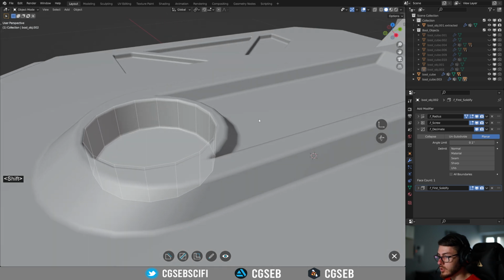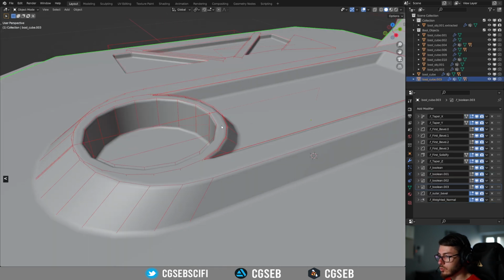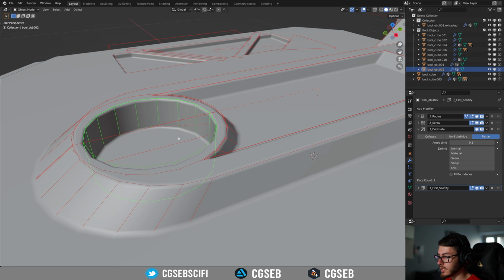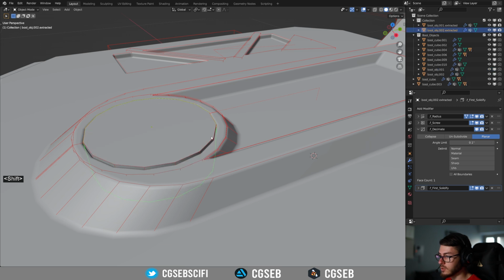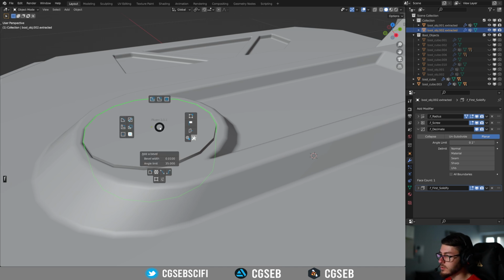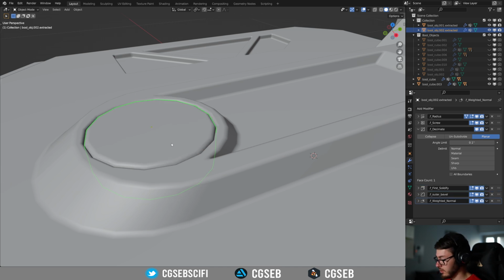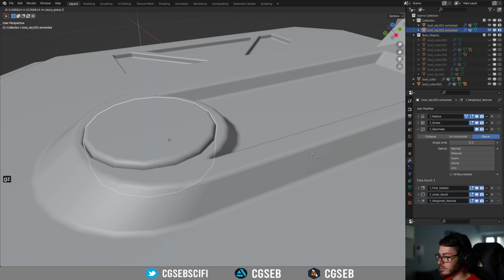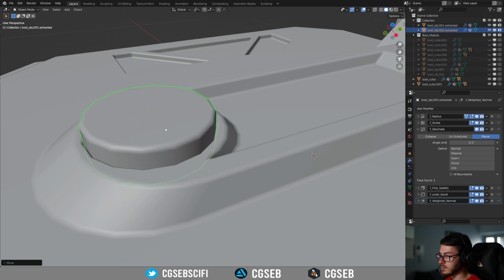We're going to right click, show the booleans, select this one, and as we did for the other part, we can just shift click on this, select this object, hide the booleans, add a bevel, and then you can just move it on the Z axis and reduce the bevel because this is way too high.